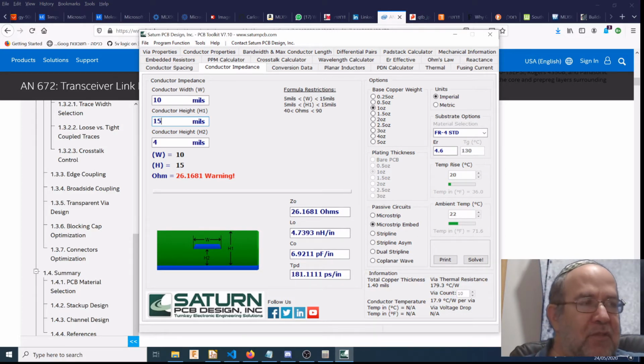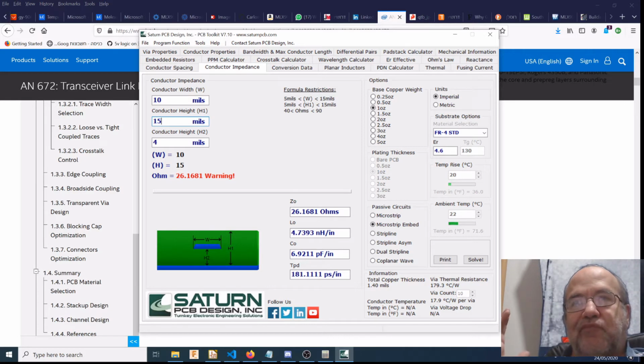As they're unable to create the original stack up, your stack up is changed, which means that the length of your vias have changed. The signal path lengths have changed. And on high speed DDR, just the change of the via can affect you.